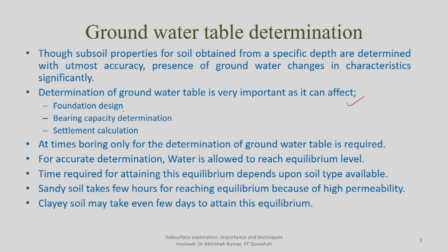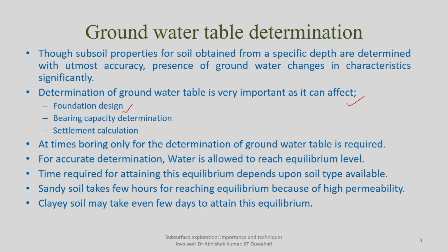First one is foundation design, as I mentioned here. Depending upon the depth of the groundwater table, at times we go for shallow foundation or deep foundation. Also, if it is a completely waterlogged area, it will help you understand whether, once you go for foundation laying, dewatering is required, whether some kind of confinement from the surrounding groundwater is required or not, and also, as I mentioned, because of the presence of groundwater table, the soil behavior changes.